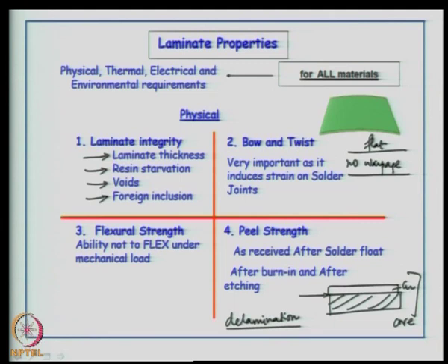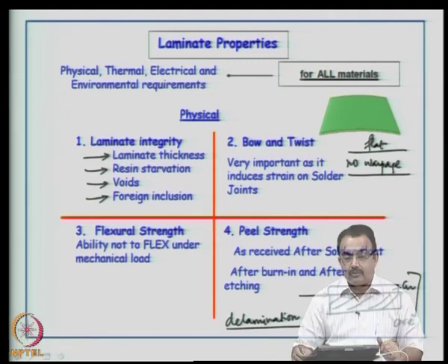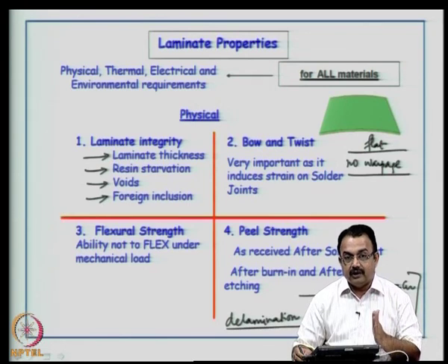They can also do burn-in test, and also during etching you can see if there is a delamination. Etching should take place only on the exposed areas of copper material to the etchant.